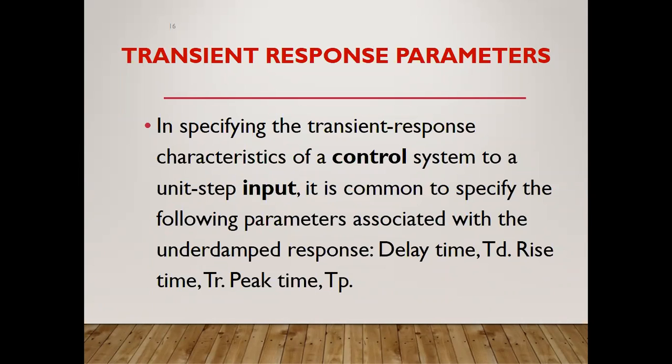The rise time: once the circuitry has started from the initial, rest, or steady state condition, it starts gradually, and the current gradually changes with respect to time and flows in all the components present, either R, L, and C, whatever it is. The time taken to rise gradually from zero up to some value is the rise time, denoted by TR.